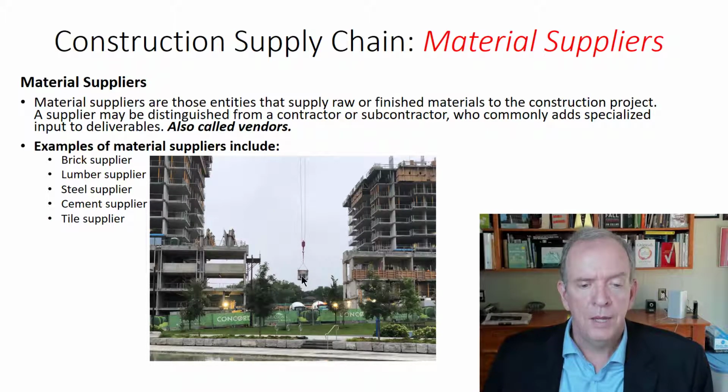It's already backed up, and they fill it into buckets, and the buckets are taken up in the crane, and the crane drops it up in the formwork. In this particular case, I think the crane puts it in the formwork for the walls that are going in on the upper floors, and then it buckets it back down. Or in other cases, it may pump the concrete to its location. It just depends what's seen to be the most efficient way of utilizing the cranes and the process on a particular project.